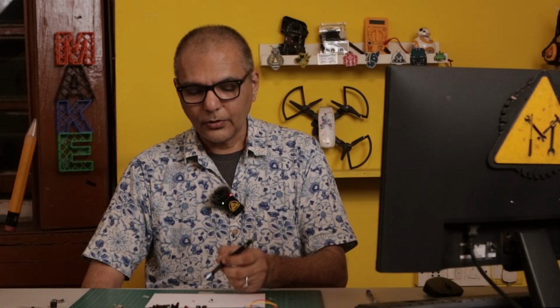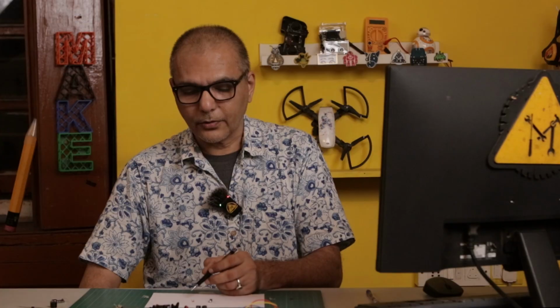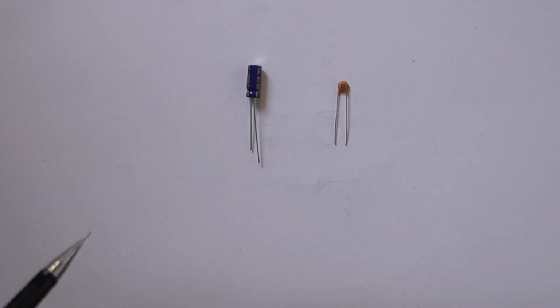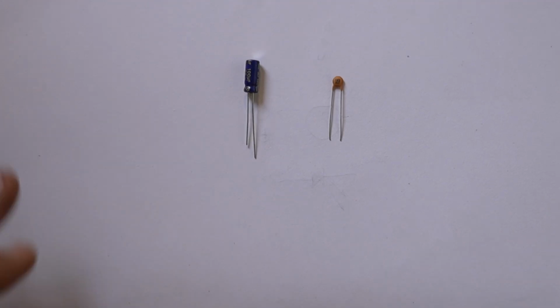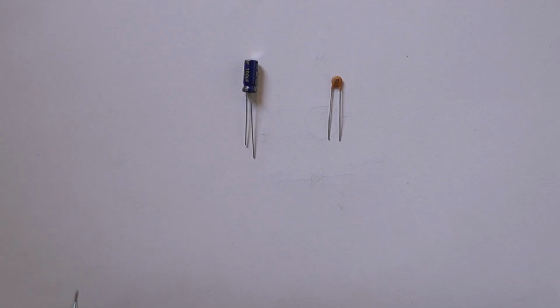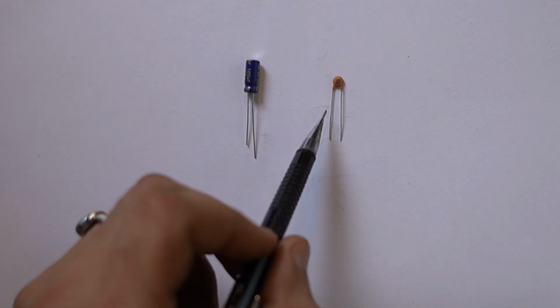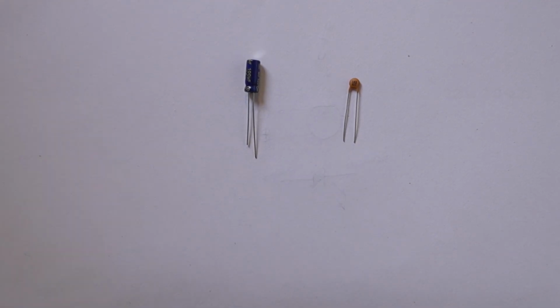There are ways of doing it in code itself. The debounce code is pretty commonly used in Arduino, but you can also do it externally by, let's say, adding a little small capacitor across your switch, which will improve the performance of the circuit by reducing the noise or the debounce. So there are many different ways that the capacitors get used. So the smaller ones like this do that.